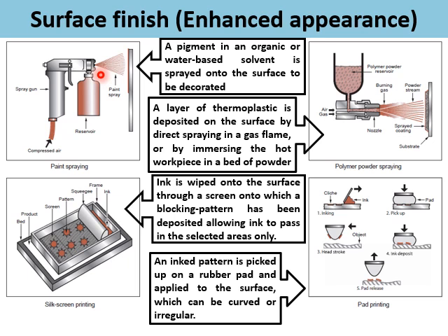Sometimes the paint is made purely from polymer. Sometimes it will be added with glass flake epoxy, so it becomes much harder. That one is for marine structures near the seashore. And then the other method would be the polymer powder, which emphasizes spraying of polymer powder and then heating. Basically, this one is similar to a thermal coating.